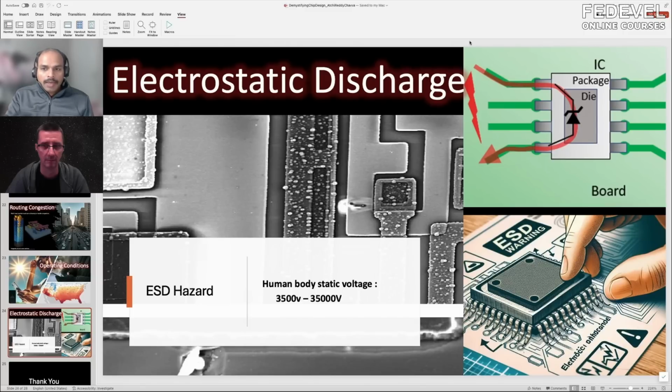And here you see what the failure would look like in silicon. Again, if you wear your microscopic X-ray lens, this is how you would see it. This is the metal structure here, and you see there's damage. It's like either bulging and then becoming open and then shorting into the neighboring structures. So basically this is what helped.